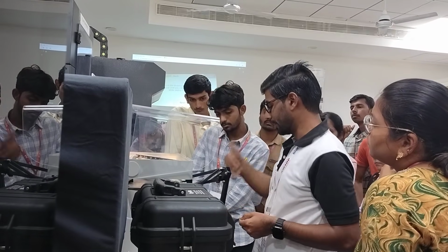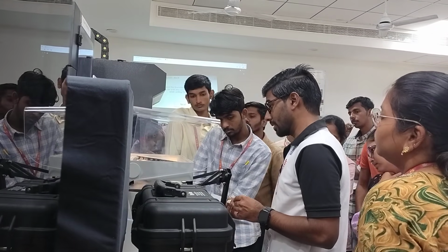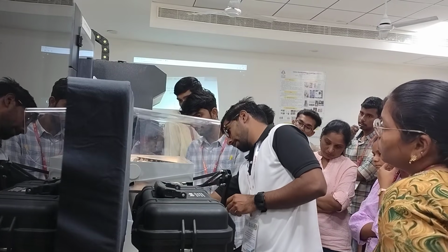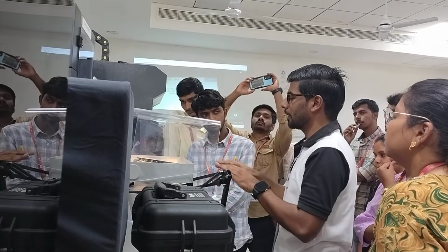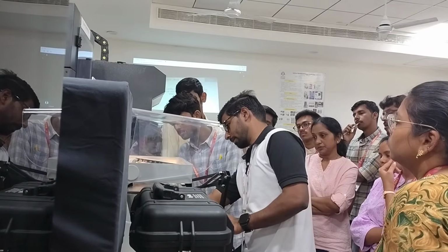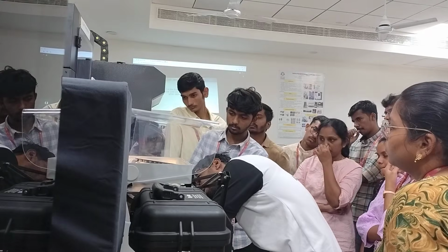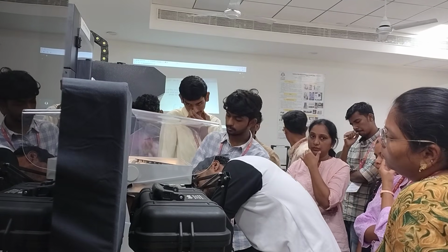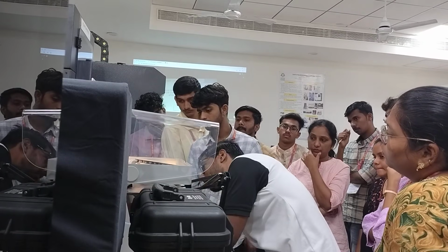Moving to the back position, that is the front, that is the back. Again, it says I have to do the same thing there also. For making a plane, how many points are required? 3 points are required. So if I adjust in 3 places, definitely my whole plane will be adjusted. The whole bed will be adjusted. I feel that this is a little bit tight. I loosen it. It must be just resistance.